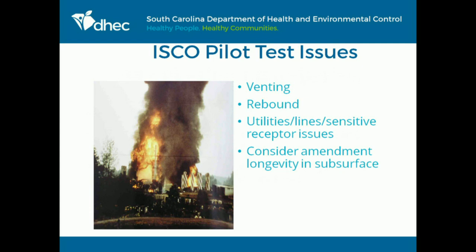In situ chemical oxidation. This is ex situ chemical oxidation here. But in situ, venting is one of those things that I think needs to be considered, especially if you're looking at Fenton's reagent. Rebound is an issue associated with ISCO, and that's something that you can look at during your pilot testing. Something else that's important is the presence of utilities, underground lines, because if you do an injection of an oxidant, you can burn up your utility lines.